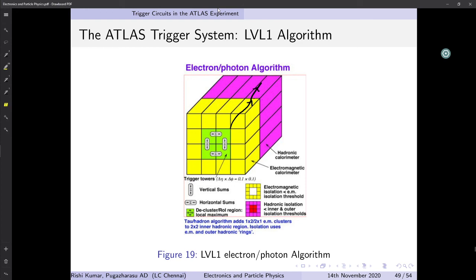Behind these, here I have something at one level, and then I have a combinatorial circuit that's sort of backed up. But even in here, before I go to these combinatorial circuits, instead of integrating them, I do vertical sums because of the discrete nature of these bits, and then I compare them with the horizontal sums and then obtain an average, and then I can talk to my trigger, and then my trigger can talk to my DAQ.